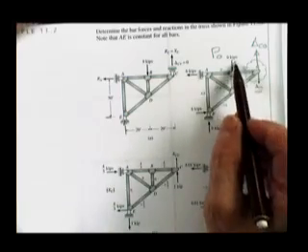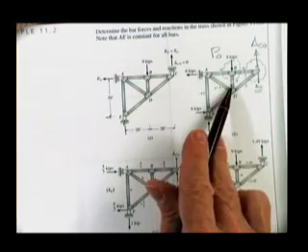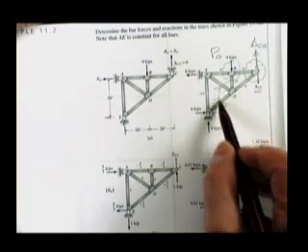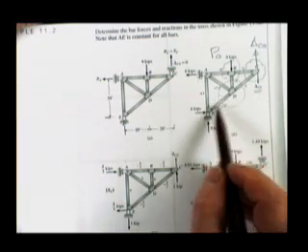Then he comes in here and you can circle out this joint. 9 down is 9 up. This is 0, so some force is horizontal, so this is 0. Come in here and take out this joint, and you could go all through the structure like that. If it's a little short structure, method of joints will be fine.